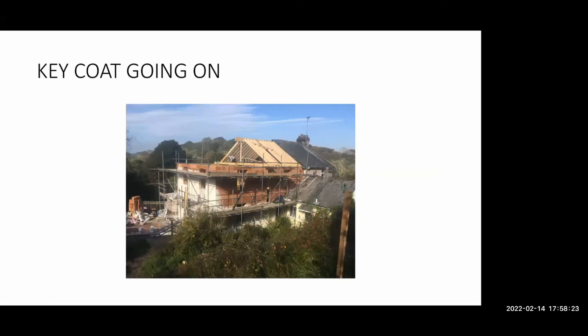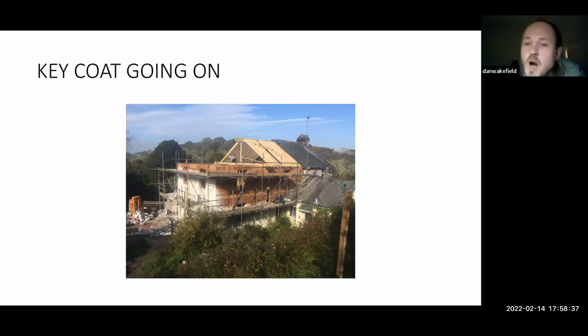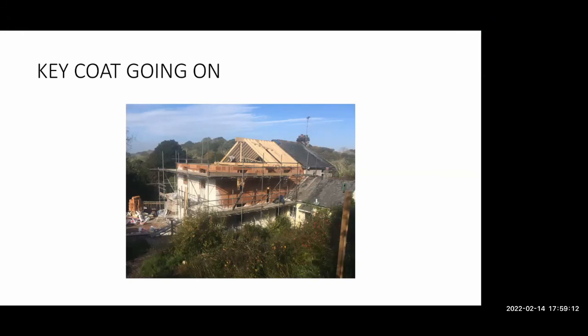Yeah. So it was a carry on from the question about insulating the concrete beam. So the cork seemed to be on the outside of the wall, which is great. But then I didn't know whether there was anything underneath that. Well, normally, above the window. So yeah, I see what you're saying. So generally, the window or the door is outside the concrete lintel zone, if you like. At that point your wall is obviously much thinner, so that's where you're not getting as much thermal bridge through, because your cork is in line with where the window sits in the wall. Does that make sense? Yeah. Okay, thanks very much, John.